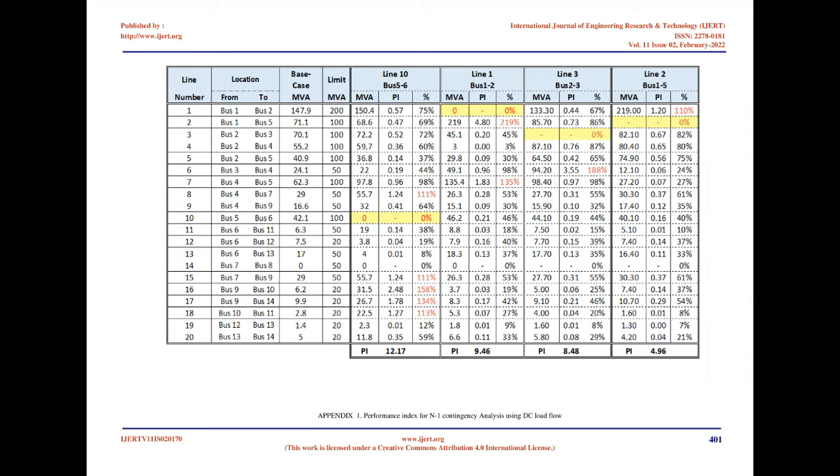C. Critical bus QV curve. In this section, I will investigate the system stability using QV curves for the critical buses and the operating zone effects for each of the buses if we apply a single contingency analysis. Figure 8 illustrates the QV curves for the most critical buses we obtained in the previous section for multiple contingency ranking. Figure 9. QV curves for the critical buses.